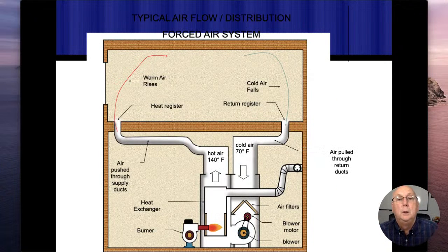All right. So here we're going to switch over to forced air furnaces. And this is actually an oil furnace. So anytime I get that blow dryer looking object in any diagram, that's pretty much an oil burner that we're looking at. And if I come up here to the right side, right above the dot there, you can see that's our barometric damper that we talked about earlier.